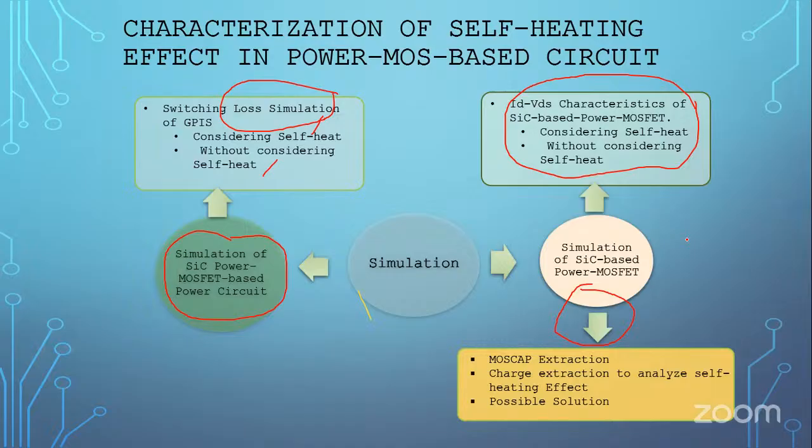In Cadence, how the MOSFET's program is done, that is compact modeling. For compact modeling, we require the device design section as well as the fabrication section. This fabrication section gives you the basically experimental result. Then we fit with the IC-CAP, give this corresponding model to the fabrication house. They make the PDK, give it to Cadence. Cadence people design the circuit, make the layout, fabricate the corresponding circuit, and we incorporate that circuit in the swarm drone and emit the frequency. That's it. Thank you very much. And now I am open for your questions.